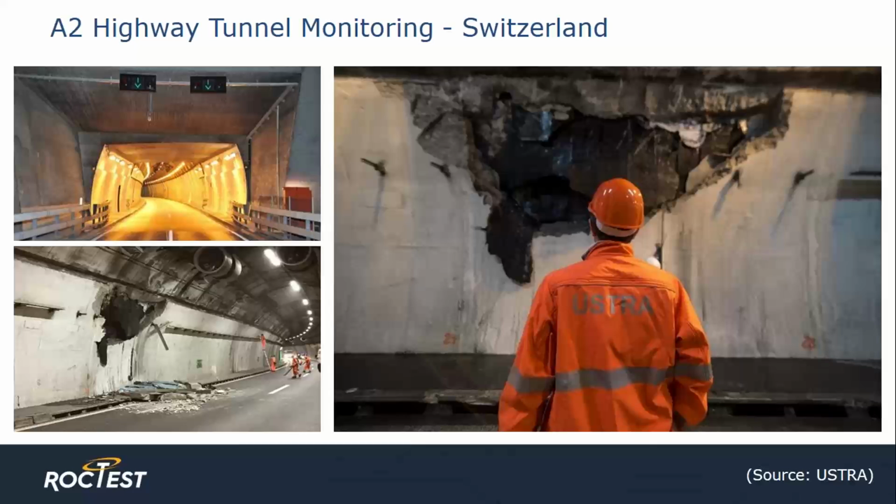Further investigation showed that the cause of the issue was meltwater percolating through the rock mass and collecting behind the tunnel lining. The decision was made to monitor both walls of the tunnel with SMARTProfile for tunnel wall deformation to predict potential failure zones. Further remediation was performed at the failure zones, installing drains.